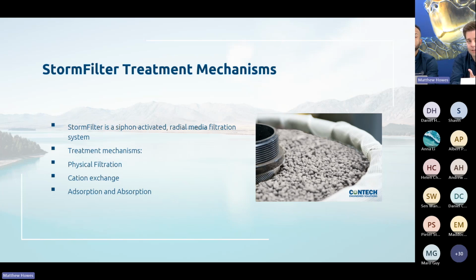There is physical filtration using the perlite media. There is cation exchange with the zeolite media. And then carbon provides adsorption and absorption of hydrocarbons and some more metal removal.